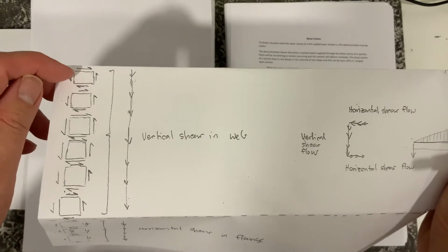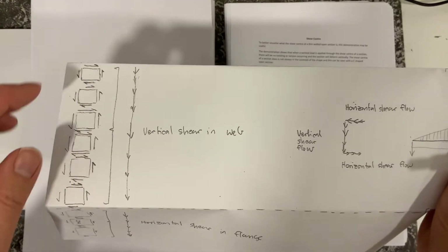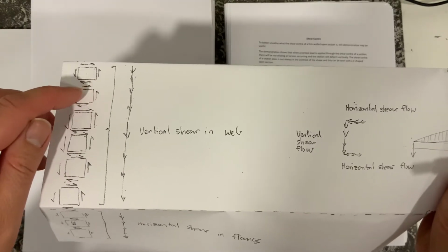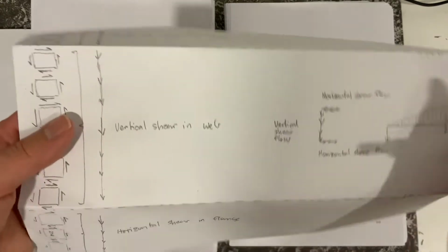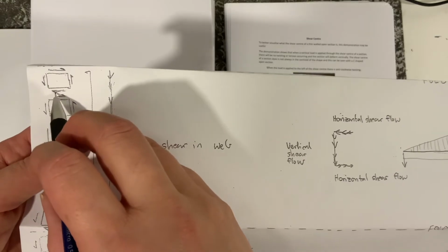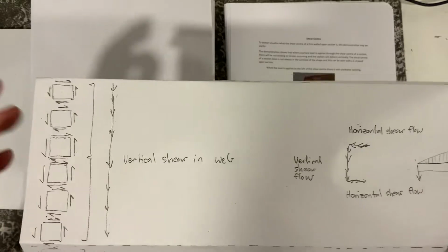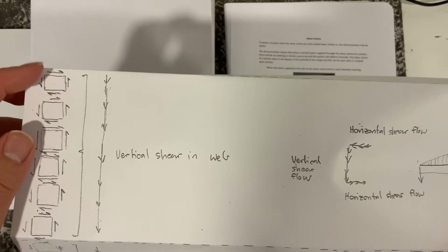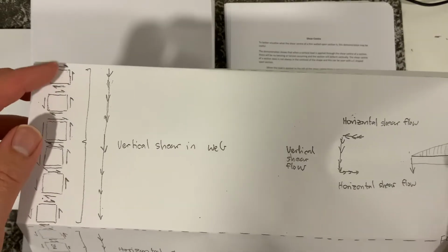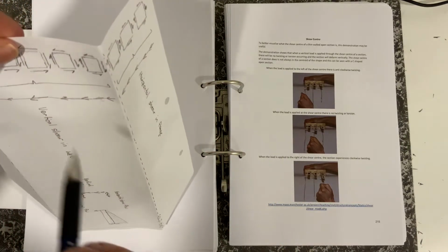You would of course get the vertical shear stresses, and these would have to be balanced by the complementary shear stresses. And on either side of each other, that shear stress is equal and in the opposite direction to the one on the next side, so they would cancel each other out. Okay, so that shows the horizontal one, and the horizontal one, of course, acts in the longitudinal direction, which is along the length of the beam.